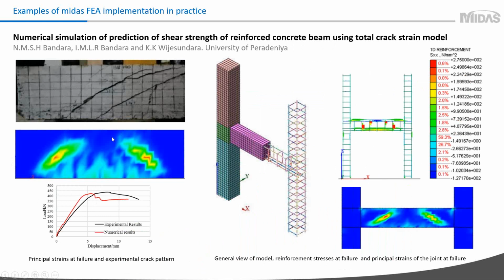Here was performed numerical research of shear behavior of reinforced concrete beams that are simply supported and connected to columns in case of a frame system. Here the user created several 3D models. He investigated them very well. He used the total strain crack model with a fixed crack, and for compression, he used the Thorenfeldt model, and for tension, he used the exponential Hordijk softening model.